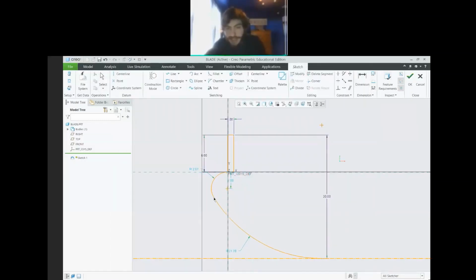We can see we're accomplishing that by how far left or right we drag the end of this first curve, and we can change, up and down, how it looks. So I'm going to say the easiest way to do that, using another constraint type, is the coincident constraint, which allows you to pick two points or two lines, and they are going to merge together. So now this point is always going to be on this vertical line, so we can only drag it up and down now.